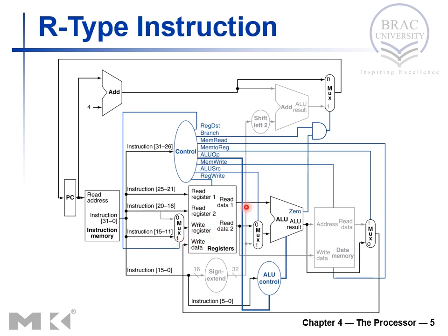Now, let's say we are executing add. So if we execute add, then let's write the add instruction here: add 10, 11, and 12. So if we write them, then this link will select register 10 as destination, and this one will select register 11, and this one will select register 12 for the two sources.